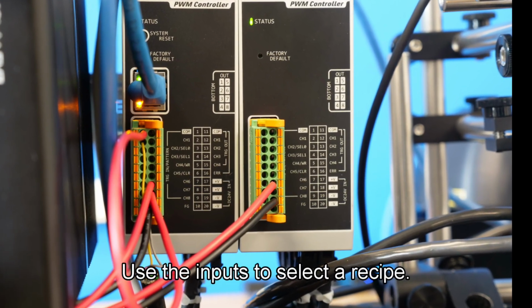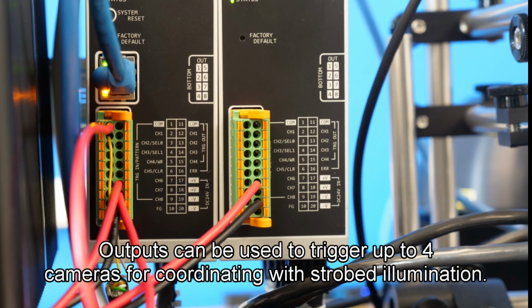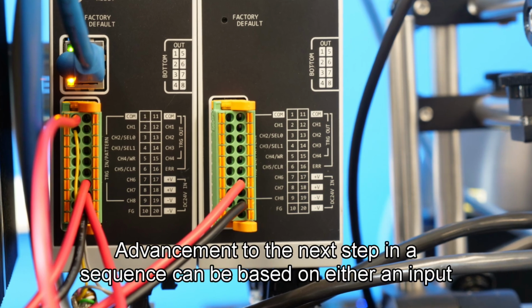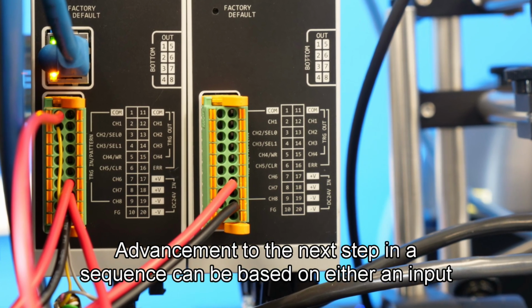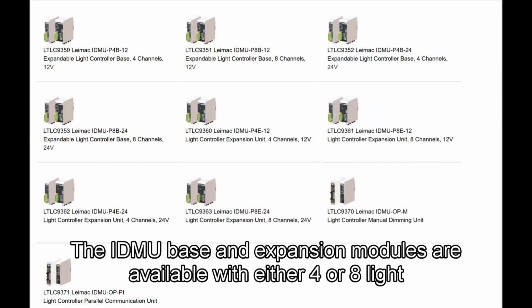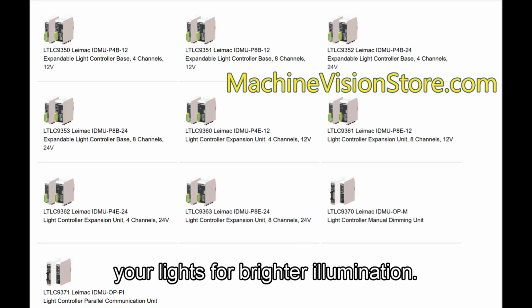Use the inputs to select a recipe. Outputs can be used to trigger up to 4 cameras for coordinating with strobed illumination. Advancement to the next step in a sequence can be based on either an input signal or a precise internal timer. The IDMU base and expansion modules are available with either 4 or 8 light channels, and there is a new 4-channel model that can overdrive your lights for brighter illumination.